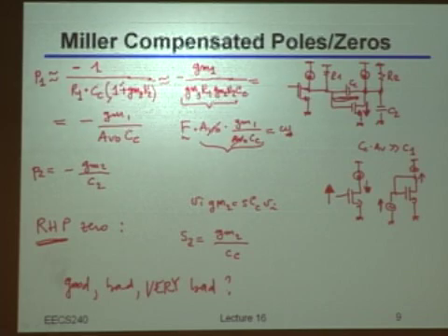But actually, it's very bad, and you know why? Because it has really bad effects, right? On the gain side, it's pushing the crossover frequency far, because you have a zero, so an increasing gain. And on the phase side, it's giving you some more negative phase shift.